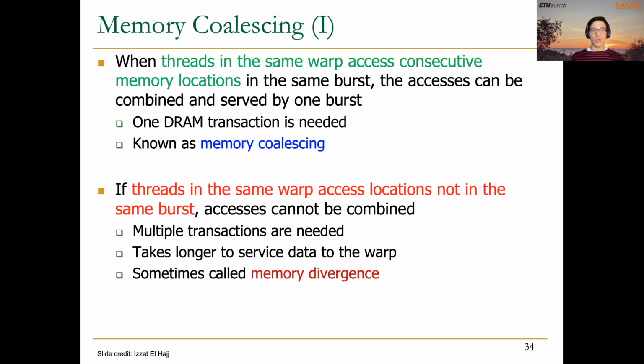Notice the difference here. If we go to memory, with one whole warp, all 32 threads of the warp want to read data from memory, we open one row, place this row in the local row buffer, and start reading cache lines from this local row buffer. If all threads from the same warp, which access memory all together because they execute together as a SIMD unit, want to get data that belongs to the same DRAM burst that is already in the local row buffer, the access will be much faster and much more efficient than if two or more threads belonging to the same warp need to access data that resides in different rows. Because if that happens, we will have row buffer conflicts, and that means we'll have to close a row, open a new row, and again pay all this long latency.